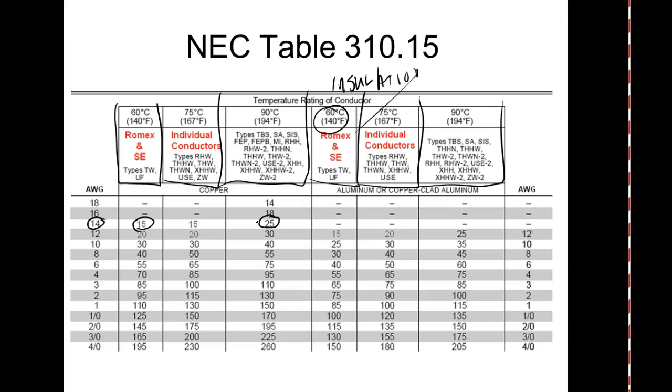So if you run the conductor through a boiler room, you have to decrease it by a certain percentage per degree. Then if you run it through the ceiling, or across the roof, you have to decrease the ampacity according to a formula that they give you. And anytime you reduce something because of a certain situation that exists, then we call that derate.